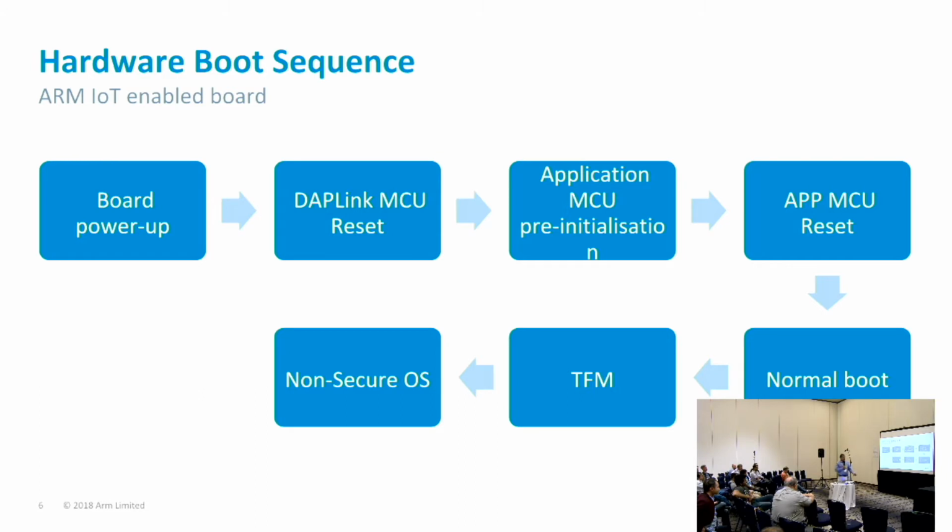I'm assuming that in production, a lot of those things will not be feasible. For example, the way that you're flashing the firmwares during the product development life cycle will lock down certain aspects. So this reference design is mostly about testing on development boards, where you are permitted to do more things than you would be on a production board.